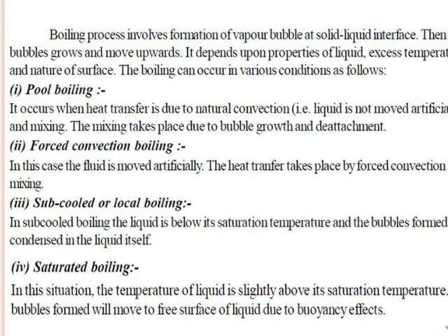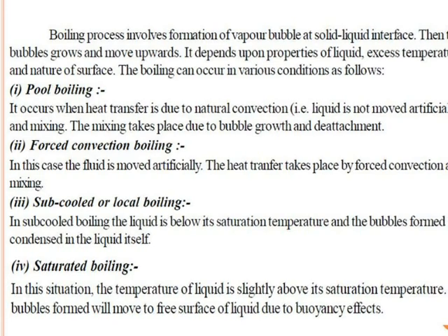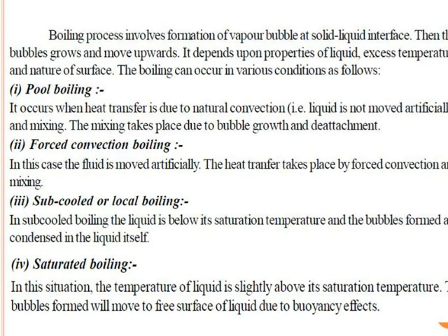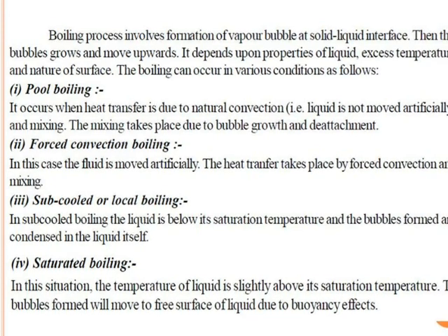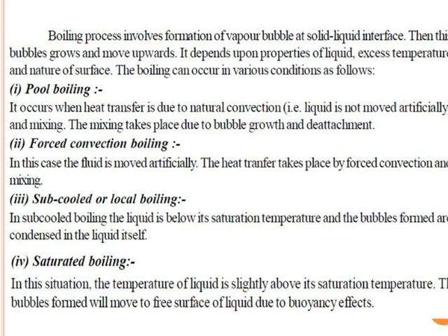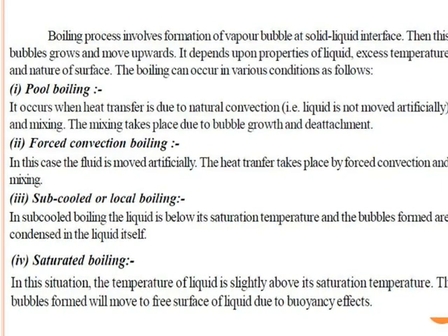The third is subcooled or local boiling. In subcooled or local boiling, the liquid is below its saturation temperature, and the bubbles are formed and condense into the liquid itself.